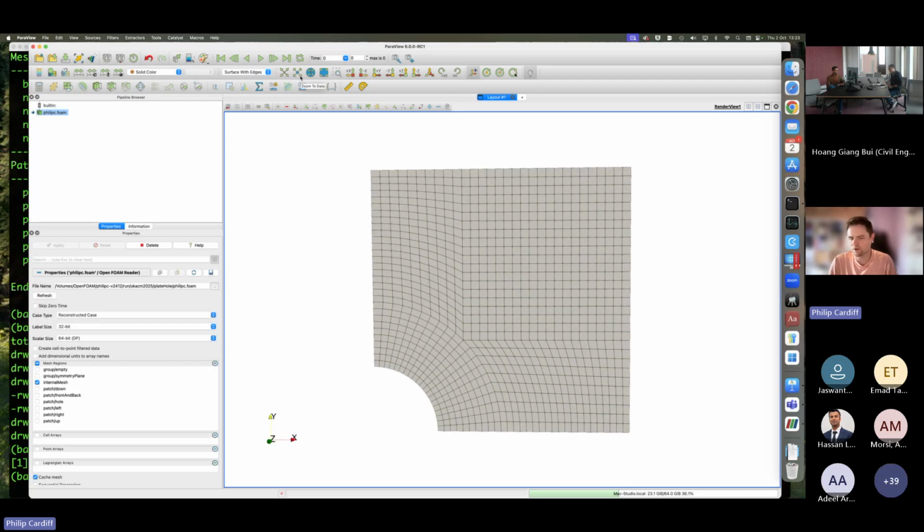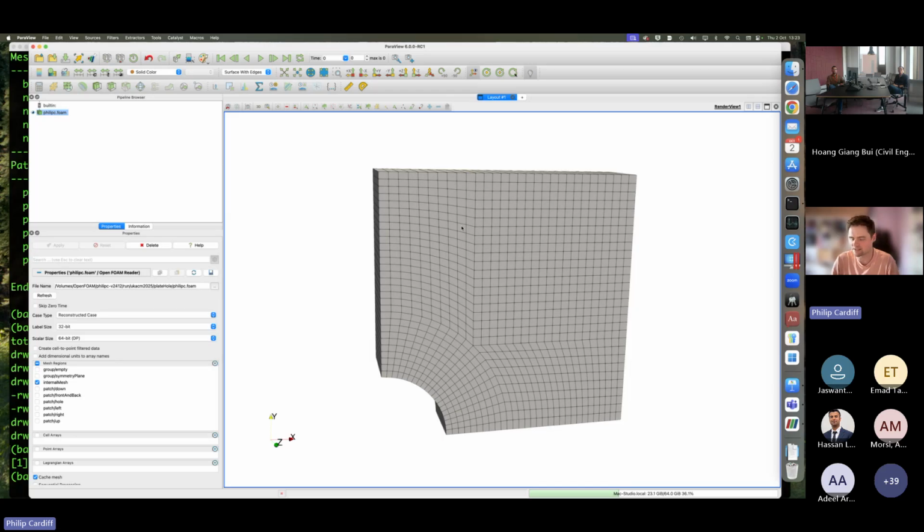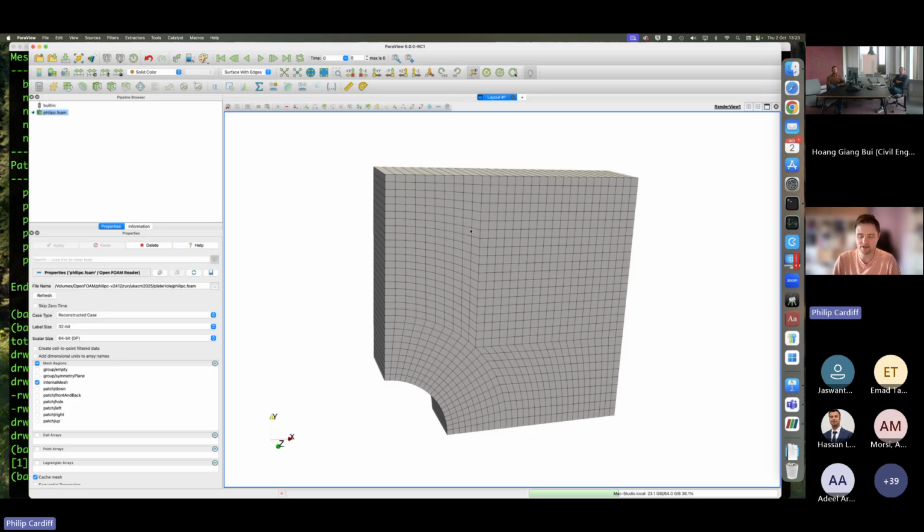One question you might have is, what kind of meshes can we use? So any mesh that's supported by OpenFOAM, you can use for the solid mechanics simulations. Of interest, which looks a bit strange if you're from a finite element background, is you can have polyhedral meshes. So you can have meshes where the cells kind of look like little footballs, basically. For example, if you use ANSYS Fluent, you can make a polyhedral mesh. You can use open source meshers like Gmsh, and that would make tetra meshes, and then there's a built-in command in OpenFOAM to make the dual of that mesh. So it will make the polyhedral version of the tetrahedral mesh. But there are other meshes. You can use commercial meshes as well by importing.